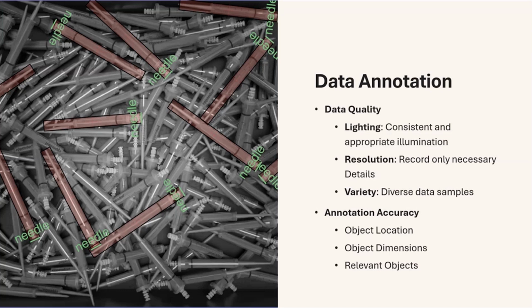You want to have a homogeneously illuminated scene, so that there are no dark spots or light spots, and the camera can capture everything clearly. You also want to mind the resolution of the camera. On the one hand, higher resolution means more processing time. It means that maybe we have to run inference on these images in patches and can't process all of the image at once. On the other hand, you still want to make sure that all the details, all the features you really want to make out on these images are visible. These are the two aspects that need to balance out.